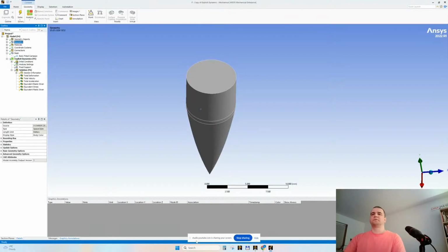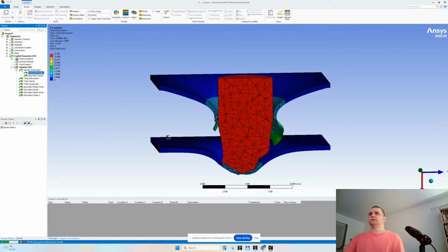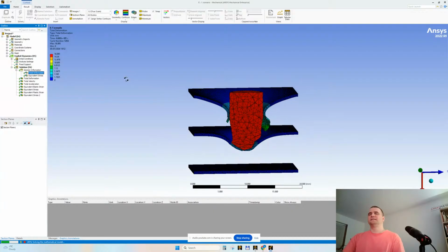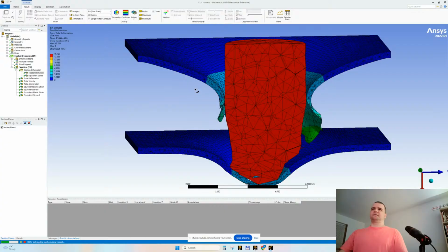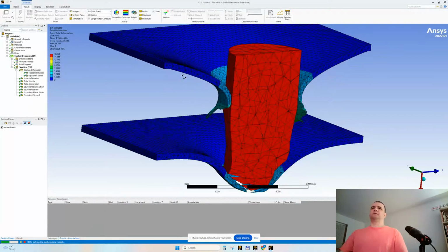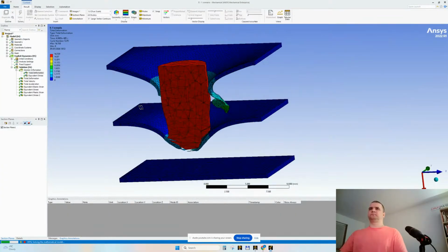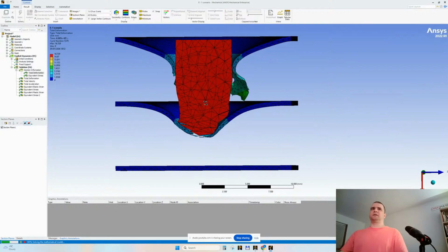Update geometry from source. 6 minutes. All right, how does it look? Yes, so we increased the stiffness of the mesh by adding more elements. And this maybe will not touch the third plate, maybe.